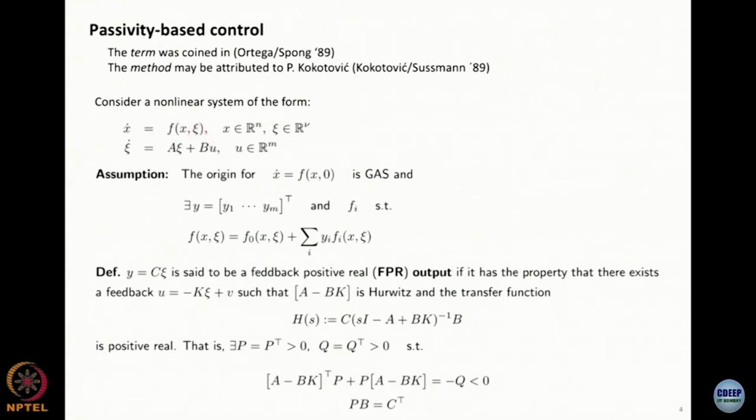So if you partially feedback linearize your system and it became like this, it is fairly easy to design u so that, if (A, B) is stabilizable, you just bring psi to 0, and that's great. But once you bring psi to 0, what will happen with the zero dynamics? That is the dynamics when psi here is equal to 0. Maybe they are unstable, and there is nothing you can do about it through the control a priori because it's just sitting there and there is no control input there. So what can you do?